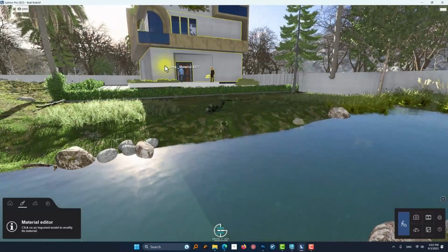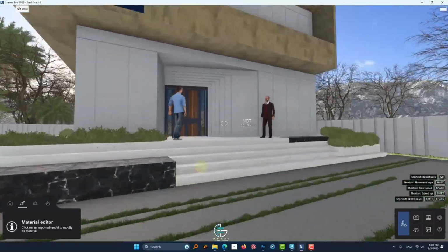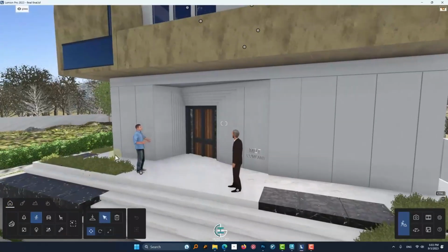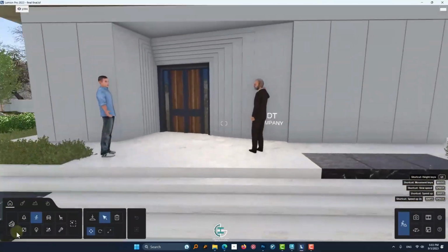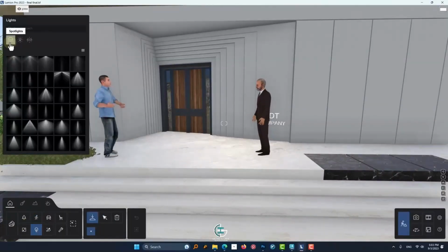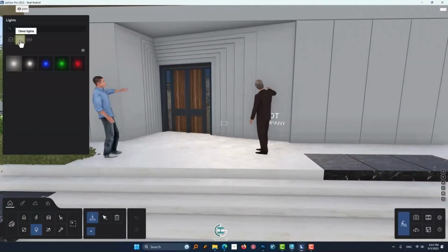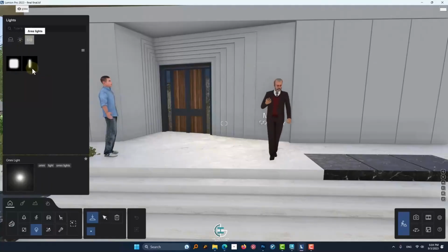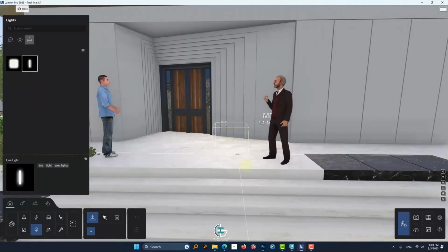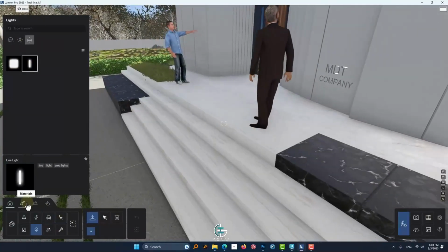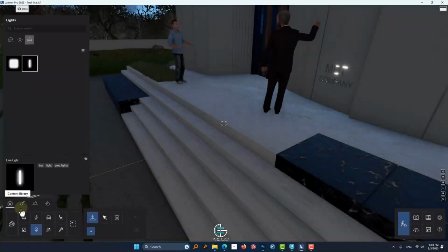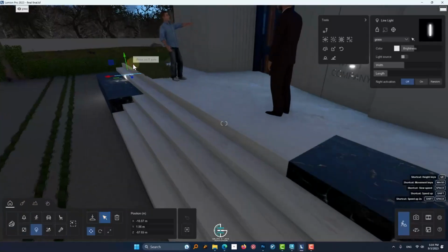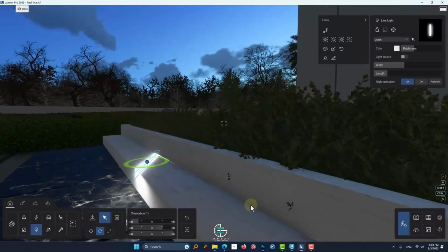3Ds Max with 2 layers. I'll hide one of them. See, it's yellow. Now we apply the material of the same soil to it, forest floor texture. I hide this one, and this one is exactly the same copy of itself. We took a copy, and we pull it down a little. I did this. Look, there is a very small separation at the bottom. It shouldn't be too much. It's impossible to work with. Look, very small. Definitely 5 or 6 centimeters.